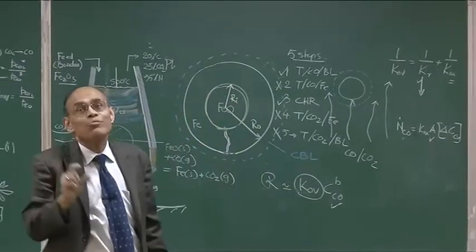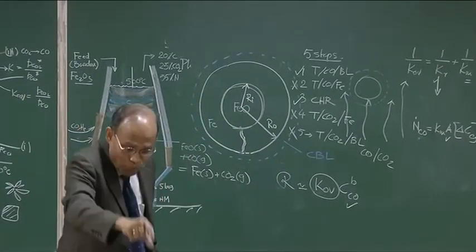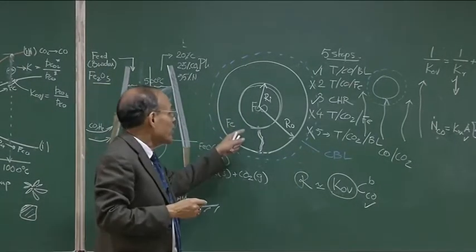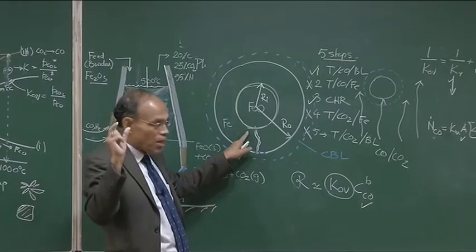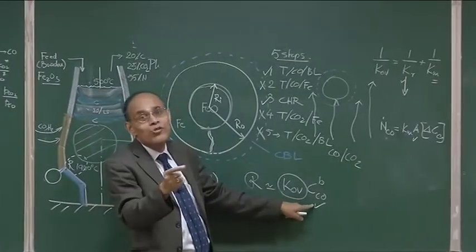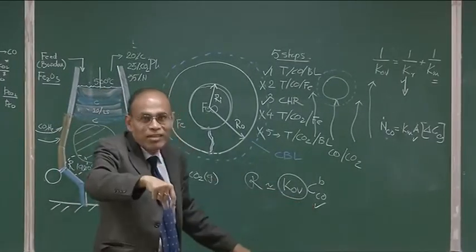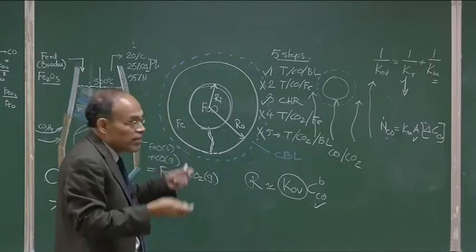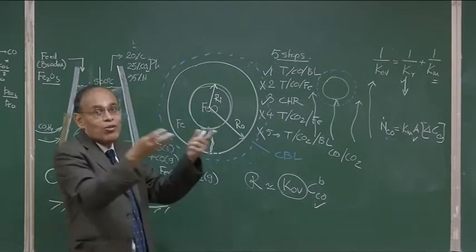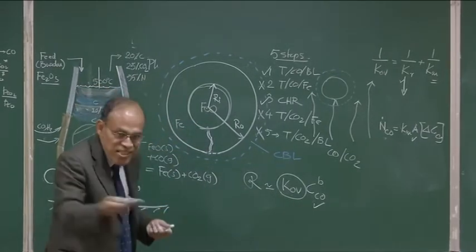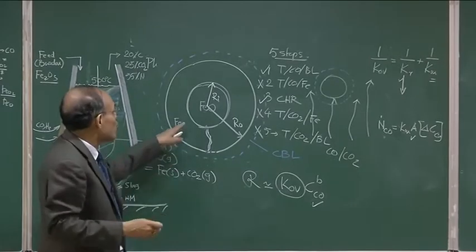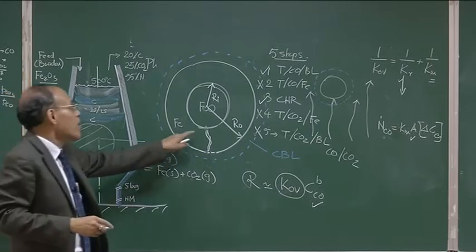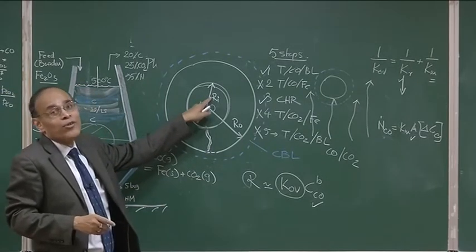how do you know that? We can take pellets out in laboratory scale experiments, which is very easy. Taking a spherical pellet out from a blast furnace is going to be very, very difficult. So, we can subject pellets to different values of CO2, at 900 degree, 1000 degree, 1100 degree centigrade. Then as a function of time, we can take out the pellet, dissect it, and look at it under a microscope to find out the interfacial area, and thereby we can measure the Ri value through microscopic study.